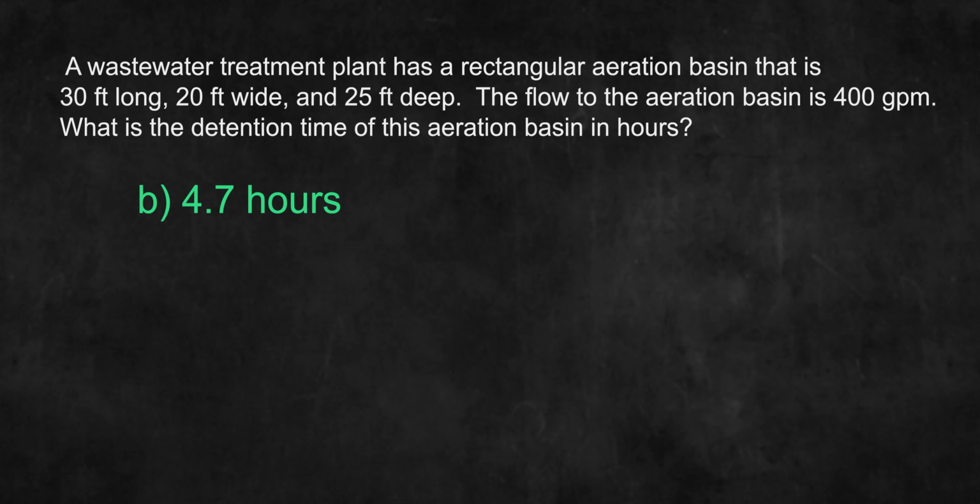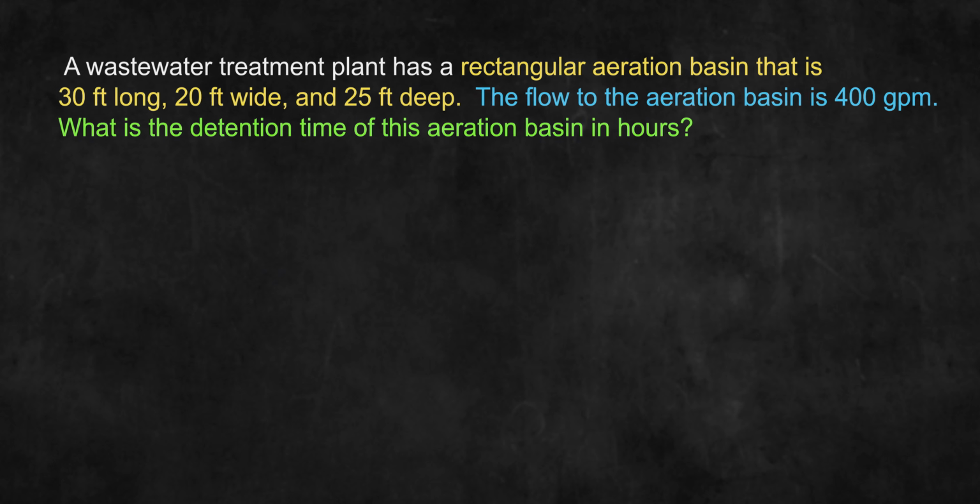The answer is B, 4.7 hours detention time. Detention time is an important concept in wastewater. How long water stays in the basins or tanks at your facility will alter how your processes function and will directly impact your plant's odors, biology, and effluent quality. This is why when your influent flow is too low or too high for an extended period of time, it can cause negative issues at your plant.